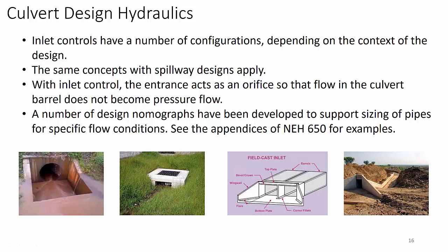Those are explicit. A more common system is the flanged or open, where you have a flared entry. So you have a wing wall, a bottom plate, a top plate, and a bevel or a crown as water enters the barrels. And so these systems can be under a number of configurations. You see one with a gradient drop and an outlet. So the design for this system is well within your tool set now.